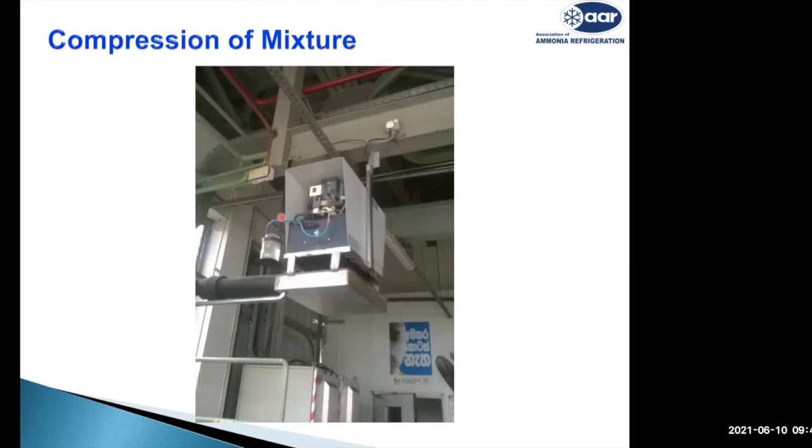If we have multiple receivers or condensers in a plant, it becomes difficult to connect one purger common to the system. You may have to use multiple purgers for multiple condensers and evaporators. Remember, in this kind of system, the drainage of refrigerant is very critical, and you have to make sure that you have properly drained it back to the system.